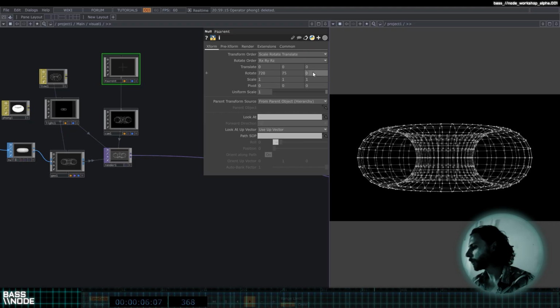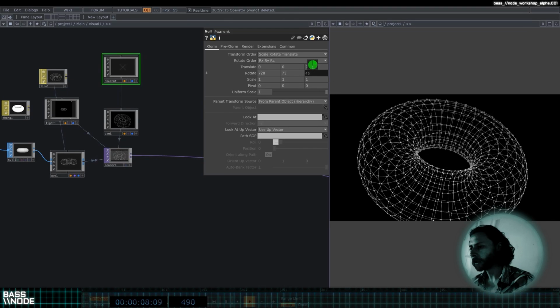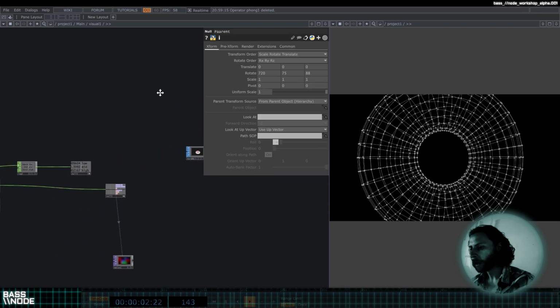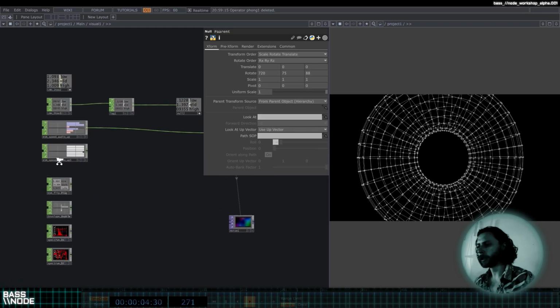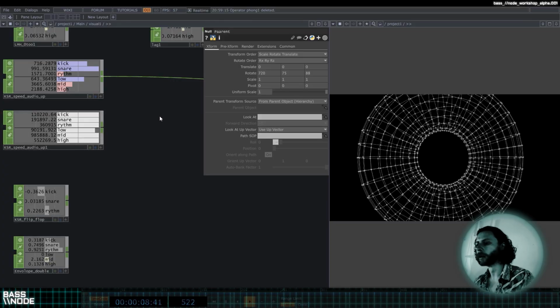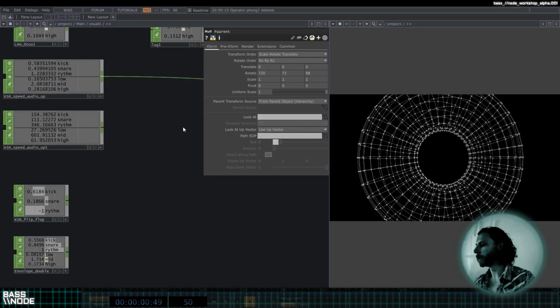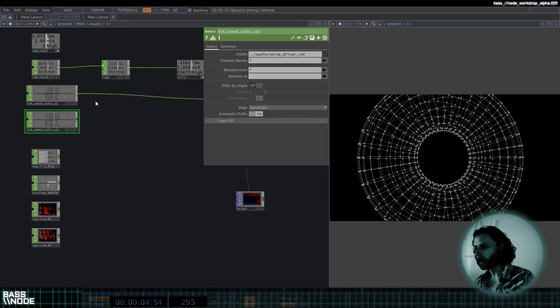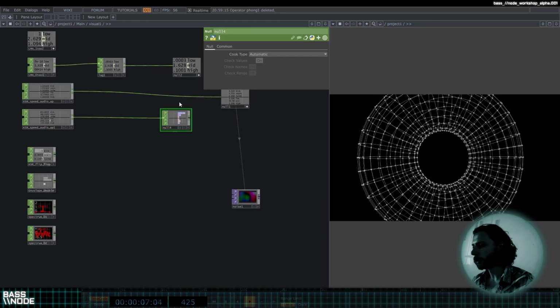To make this audio-reactive, all we need to do is grab our chop data from over here. And this is the noise driver that I was talking about. I'm actually gonna hit 1, which is set up to be a reset for everyone here because that value is a bit high. And I'm gonna hit Alt-N to bring out a null.